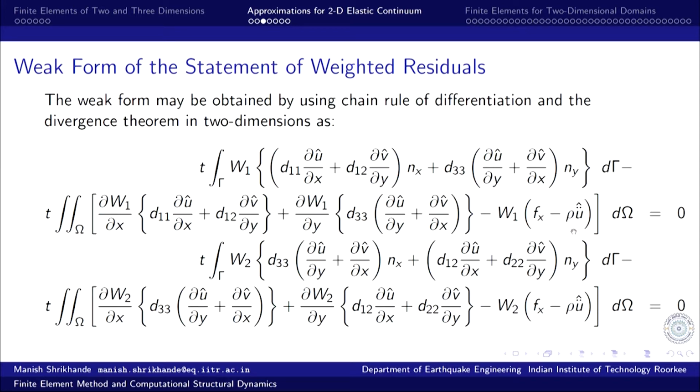These are the inertia terms that govern the dynamics of the system if the system is subjected to rapidly changing loads or time varying loads. Since in this particular case we are not looking at time varying loads, this calculation will not be required; otherwise it can be computed in the same way as other domain integrals.